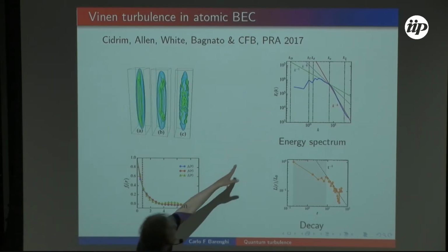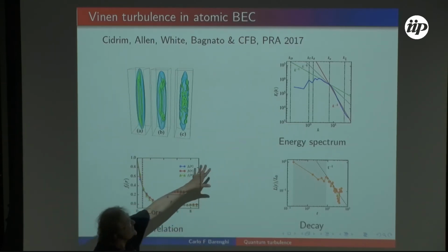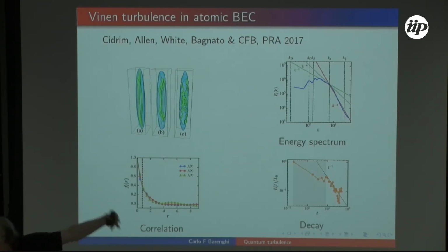Yeah, that's right. So what happens on the left? Now, as I said, the boundaries become important. If you have a periodic box, then everything repeats periodically with your box size. So if you have turbulence, the energy spectrum will go to the maximum value to the left, because the largest eddy would be essentially a big vortex as big as the box.